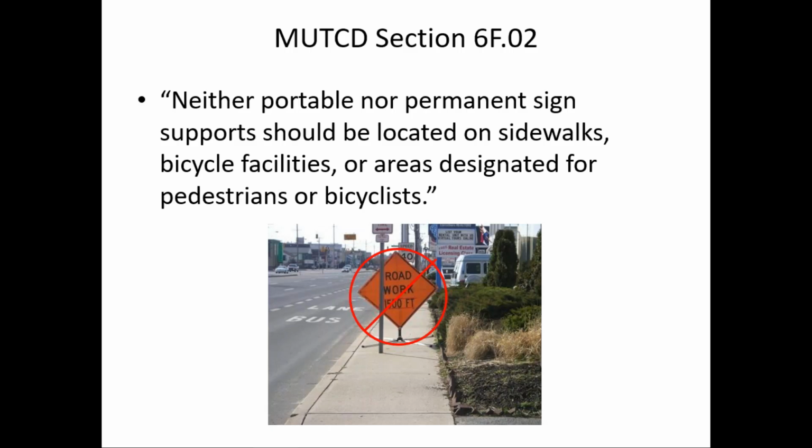It looks like there's a bus lane immediately adjacent to the curb, so we can't put the sign there. Looks like there's some landscaping and such, shrubs at the back of the sidewalk, that may make it difficult to put the sign there. But in addressing these, we should remember accessibility and the PROWAG requirements as well. But I recognize it can be tough to try to satisfy both criteria.